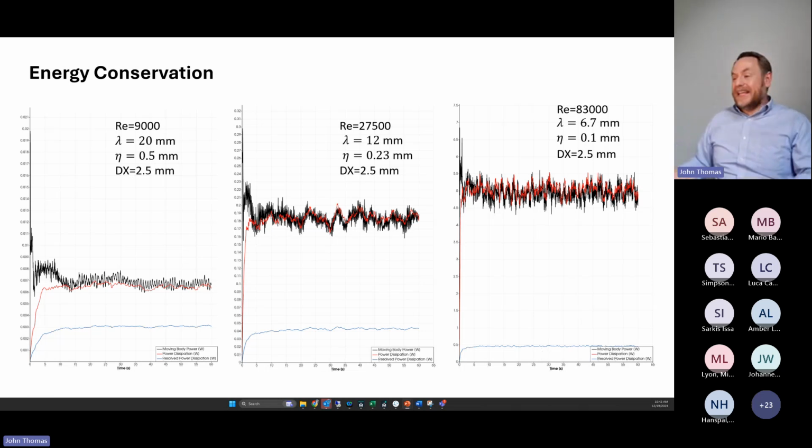Less than 10%. And again, it's a neat way to interrogate this from the other direction. Here I'm keeping resolution fixed and changing Reynolds number and seeing, aha, I'm still conserving the first law, and my total energy dissipation rates are correct, as it were. But as I change the sand beneath the feet of the simulation, feet being the resolution here, I'm actually moving the magnifying glass as to how much of the energy I'm resolving explicitly.